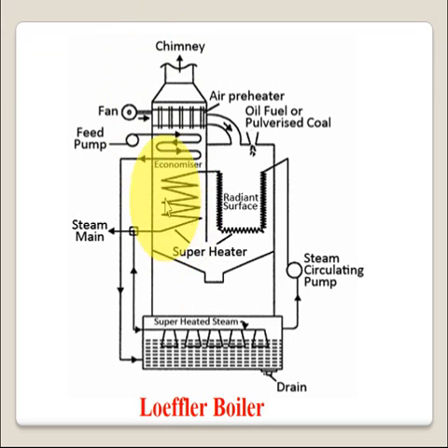The superheated steam generated in the superheater is partly supplied to the steam HP turbine and partly supplied to that drum. Around one third of the steam generated is supplied to the turbine, while two-thirds is used to generate steam in this drum.